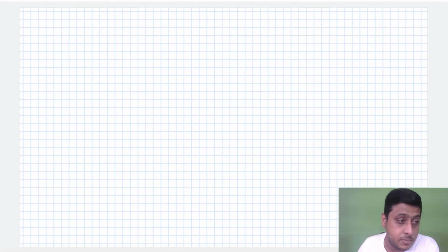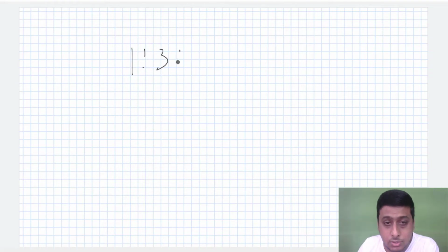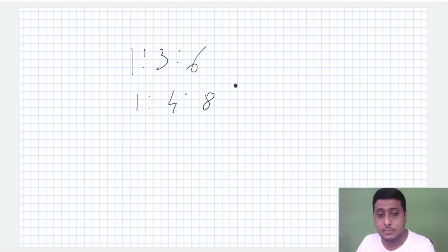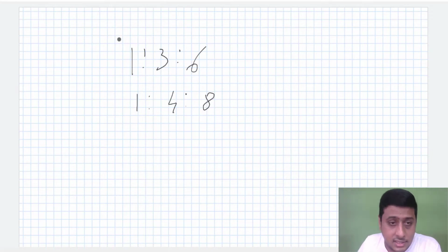Next comes the PCC. What is PCC? It's plain cement concrete. Generally the ratio will be 1:3:6 or 1:4:8. It depends upon what the structural designer gives. Even the thickness of the PCC varies. This one is the PCC.